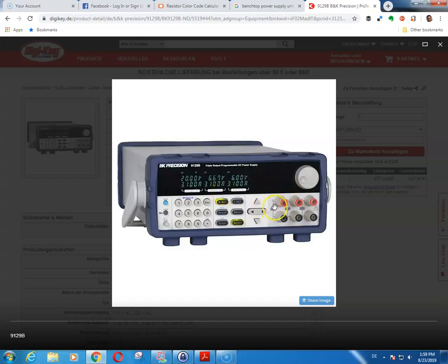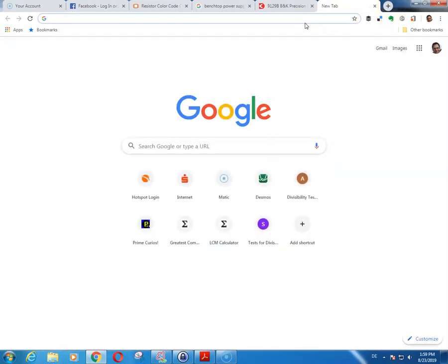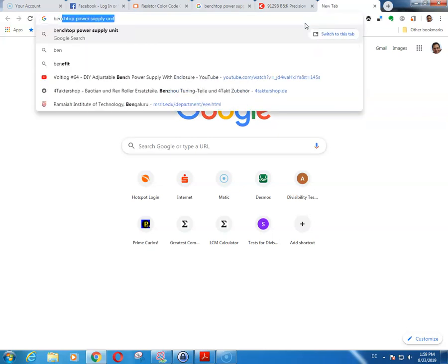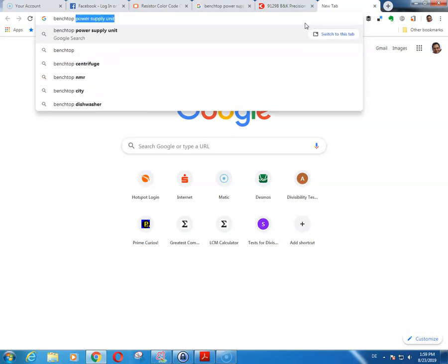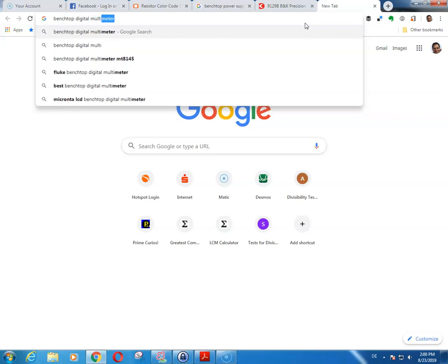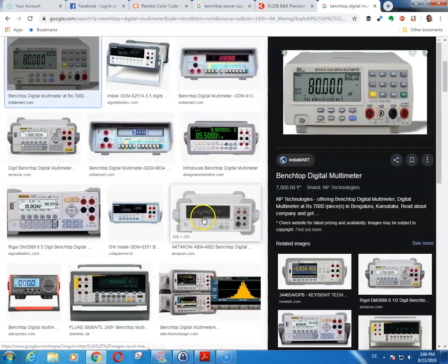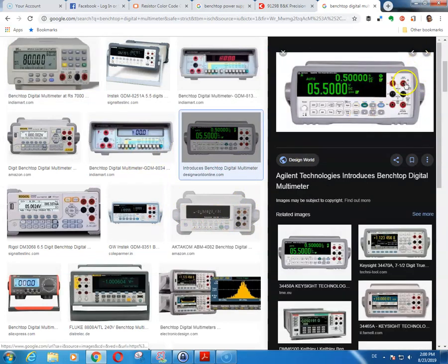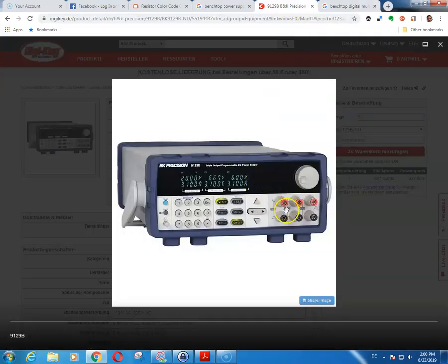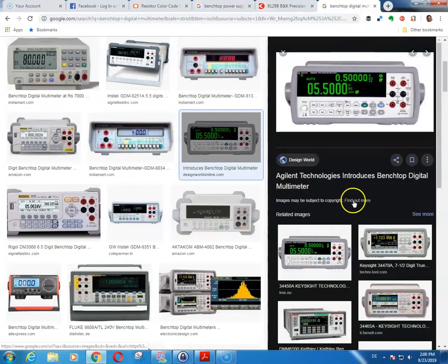That of course you cannot see, but you can measure it using a multimeter. If you search for a benchtop digital multimeter, you would get something like this, and this is a multimeter. You can think of the outputs of your voltage source as a battery. Using two pieces of wire, you can connect these outputs to these inputs over here, and then this multimeter tells you what's the voltage on these two terminals over here. That's how you measure a voltage.